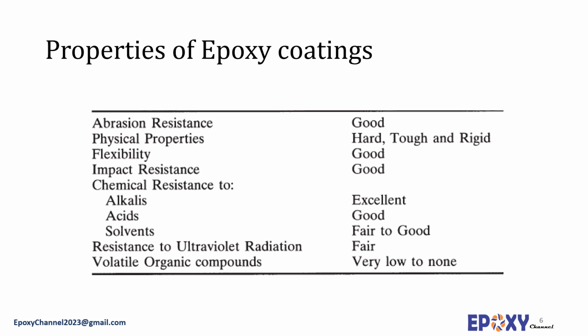In addition, cycloaliphatic epoxy resins do not contain chlorine and other halogens, which makes them a perfect choice for electrical applications. The plethora of curing agents available for epoxy curing is also a merit in the formulation of epoxy coatings. In fact, by employing the right epoxy resins and the proper curative, it is possible to formulate an epoxy coating system to meet almost every specific requirement.